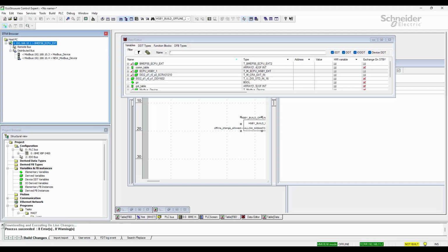So very important here is that you want to do changes that you are able to do by doing a build change, and you never want to do a rebuild all project. This will most likely make this whole procedure fail, and you'll have to upload back from the primary, transfer to the standby to get an equal system again.